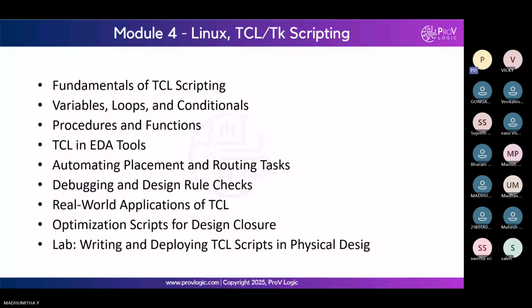In the synthesis time, sometimes the time comes negative, and how do we solve it? When clock period is 10, waveform is 5. How to solve this when generating the netlist? Sometimes time comes negative, and how we solve it? Okay, we'll be adding buffers and inverters to fix timing violations.